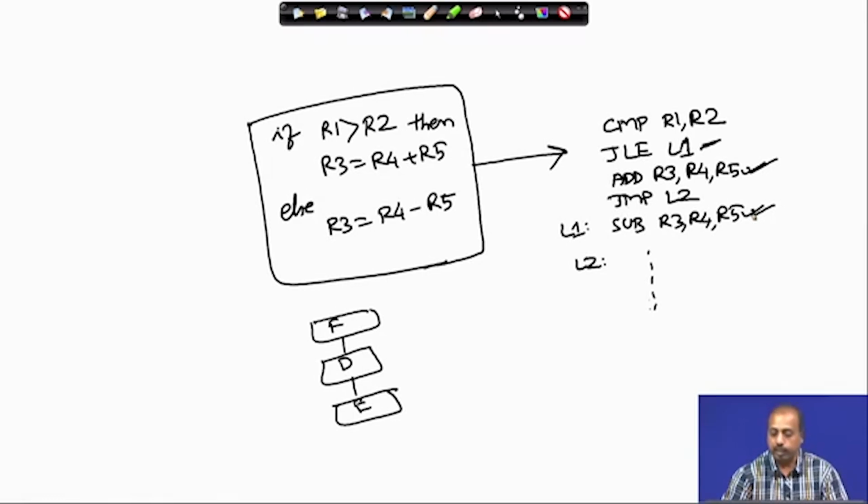For an unconditional jump, like here, there is no problem, because we know that after this instruction it gets the jump L2 instruction. So after this one has been executed, it should fetch from this address. But still you need to have that intelligence. When this instruction is in the execute phase, then the jump L2 instruction is in the decode phase. So at that point I do not know what is the next instruction to fetch. The next instruction should be in the fetch stage.